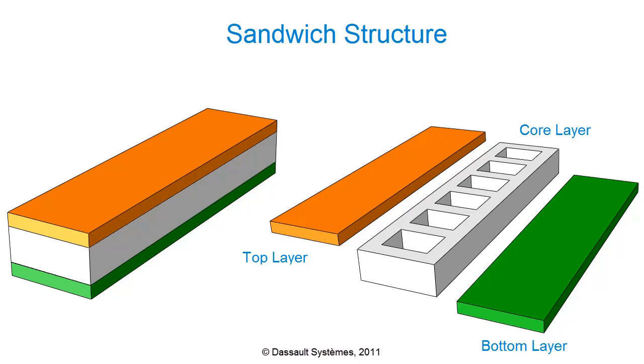The plates of a sandwich structure can be fixed to the core using adhesives, welds, fasteners, or other methods. In this example, we do not wish to model the adhesive, fastener, or weld, just the fact that the surfaces are constrained together. The tie constraint will be ideal for our purposes.